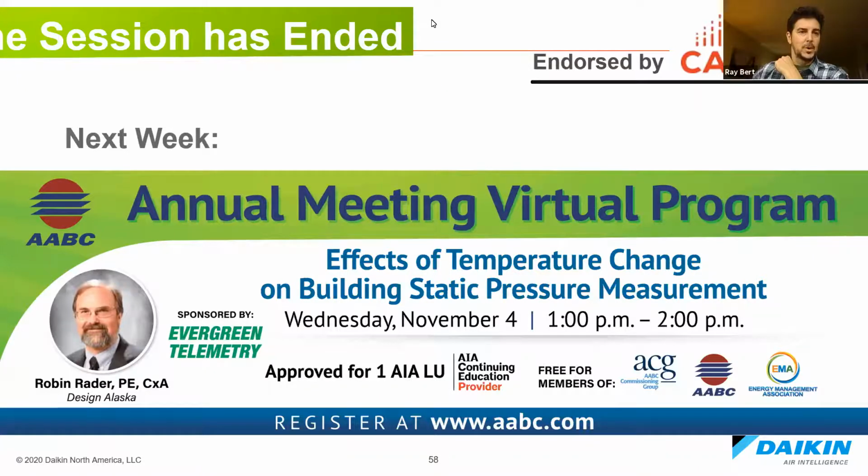Okay. Please cover how the VRF system can provide alarms to the facilities staff when it notices small refrigerant leaks. Well, we don't sense for refrigerant leaks. What you'll probably see, depending on how big the leak is, is performance issues. Of course, your rooms aren't going to cool off or heat well, but there will be other codes that would pop up in the system as far as high discharge pipe temperatures, depending on which code it sees first. But we don't monitor refrigerant leaks. We monitor through the sensors.